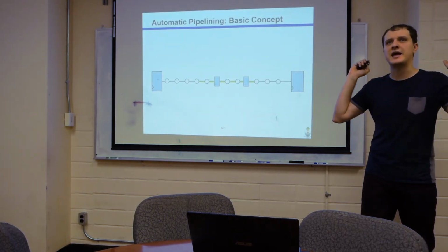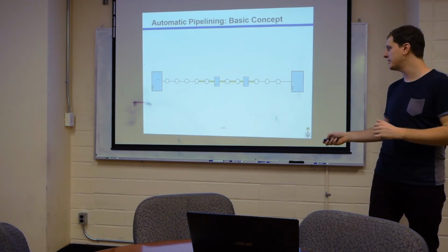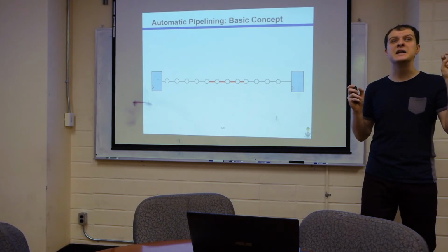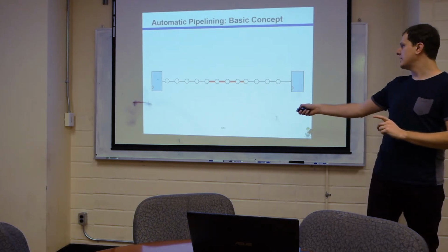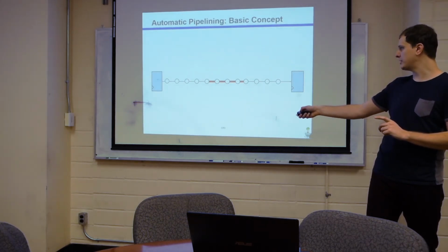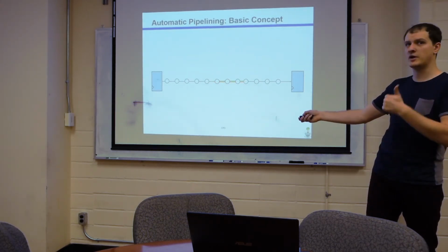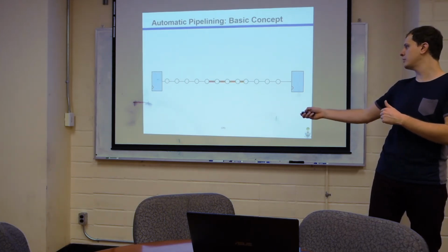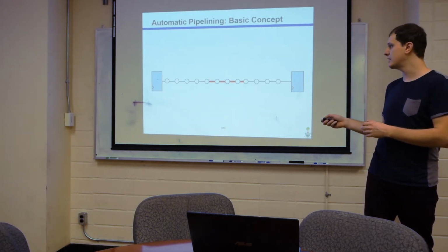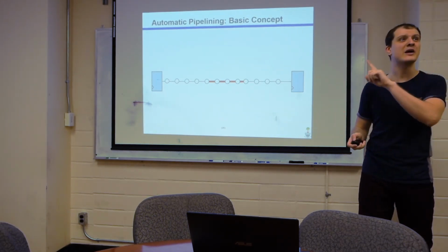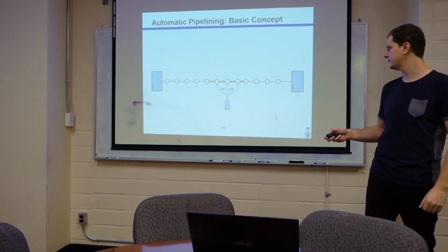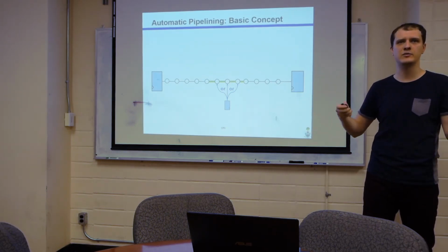So instead of just any segment that's overweight, let's instead consider a more conservative, smaller segment, something I call minimally overweight. What this means is, if I were to remove either the left or right end caps from this path, it would suddenly become acceptable. So that makes it acceptable, and that makes it acceptable. So in such a minimally overweight segment, I can now guarantee that by inserting 1 register anywhere inside there, it will be successfully pipelined. So I can put it here, here, here, and I can guarantee that it will be